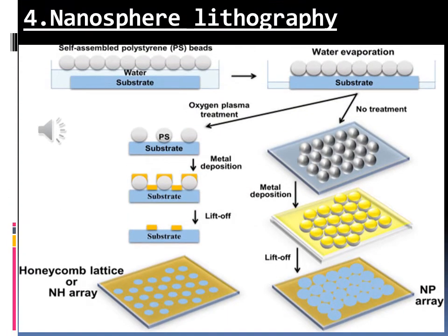In nanospheric lithography, a set of required nanospheric films on a surface is used as a mask. The nanostructures are dispersed into a liquid, known as a colloid. Depending on the surface properties and the type of media used in the colloid, the nanospheres will self-assemble into an ordered pattern. There will be an empty space between the nanospheres, which is repeated regularly over the whole surface,